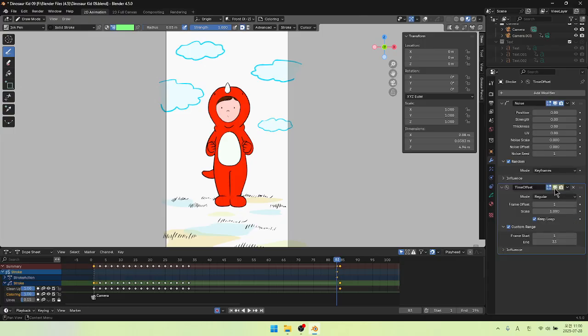If you only put the keyframe on this, the render is still going to be on and keep continuously looping the animation. If you want to disable it, you have to keyframe this camera icon as well. Come over to the next frame, and right now my auto keying is turned on, so I don't have to right click on these icons anymore. All I'm going to do is left click and turn off all these settings. Now it's all keyframed.